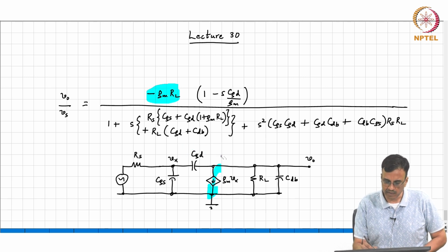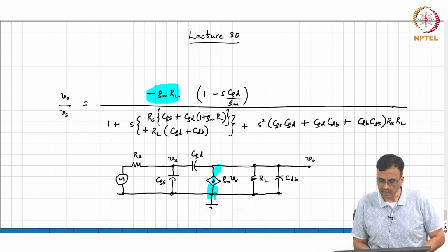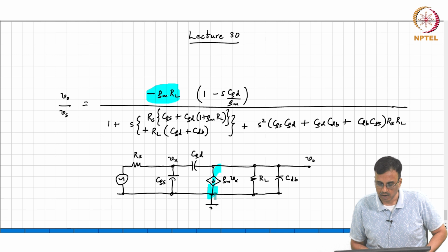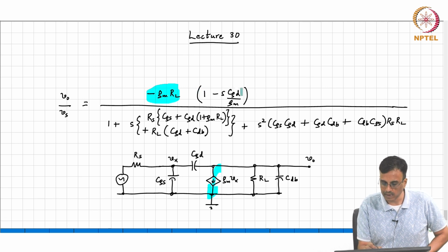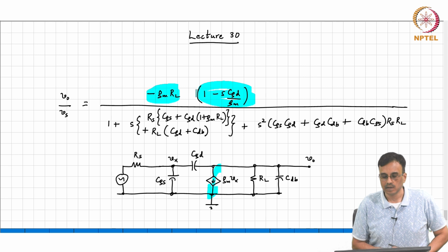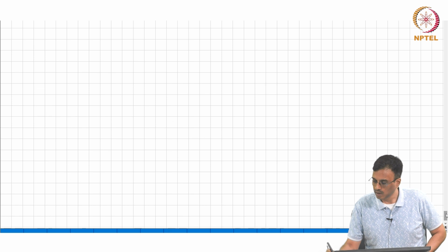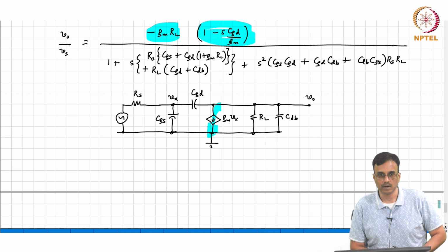And here you can see that the path gains are, one is through CGD, which attempts to pull the output voltage up, whereas the transconductance GM attempts to pull the voltage down, right? So we see that there is a 0, and because the signs of the 2 paths are opposite, it is now intuitively clear why you must have a right half plane 0. All right. Okay. So now it's the turn to look at the denominator, right?